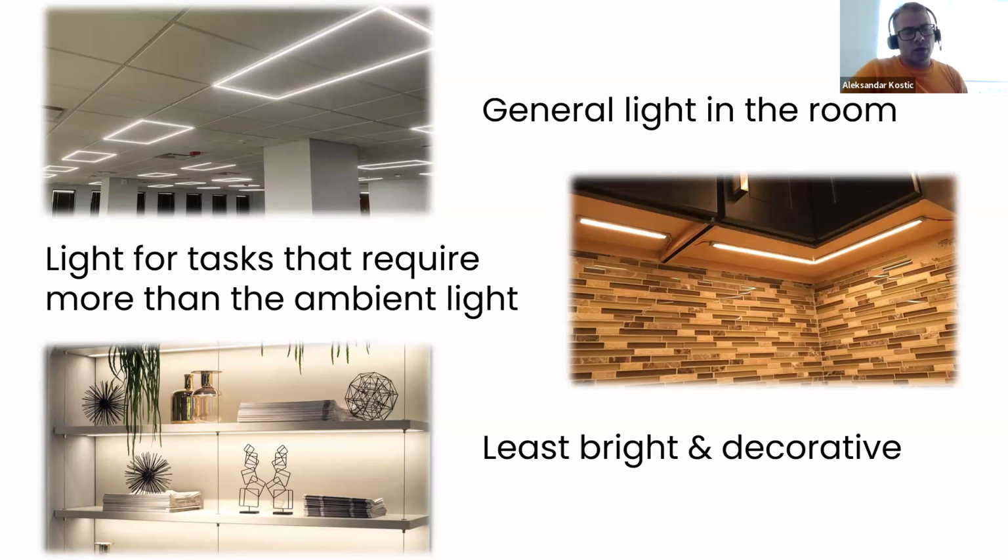for decorative purposes. So any kind of light and any type of LED tape, whether it is just white LED or colored LED, can be fully integrated and managed through Control4. Depending on the type of light we need to use in our project, we have different LED tapes which provide different features. The simplest LED tape is of course fixed color LED tape, where you have just the option to change the brightness level of the color, which is predefined.